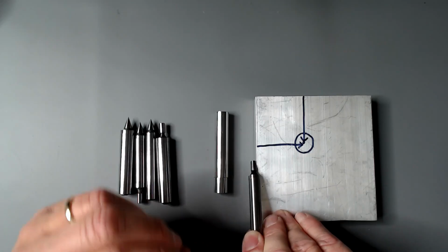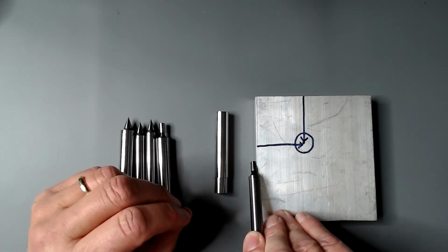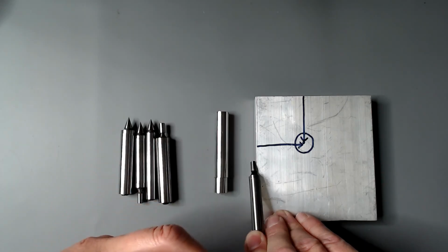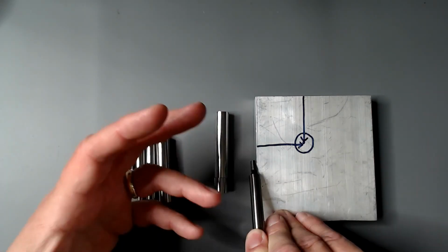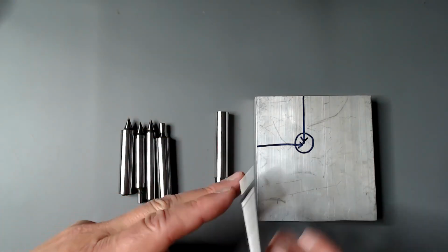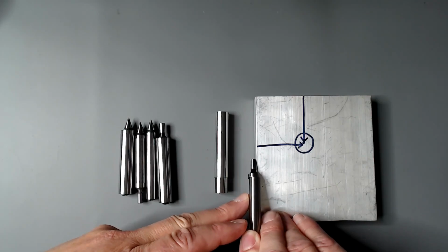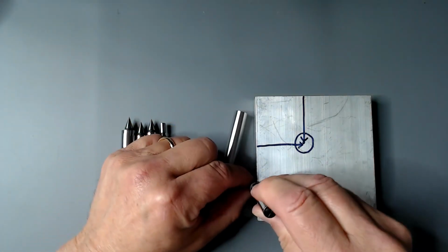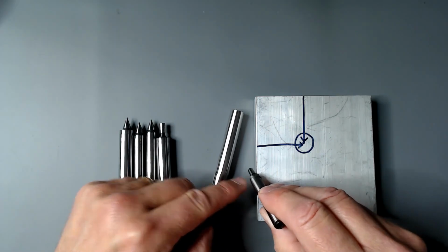But by eye, you really can't differentiate if it's running perfectly true or it could have maybe 0.0005, five tenths of a thousandth, wobble to it. But the magic of it is, as soon as it comes into proper full contact, it's going to kick out to the side while it's rotating, and that is your indicator that you are in perfect contact with the edge of your workpiece.